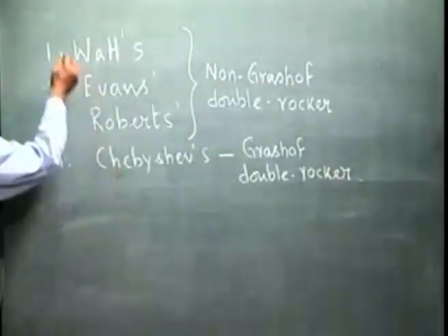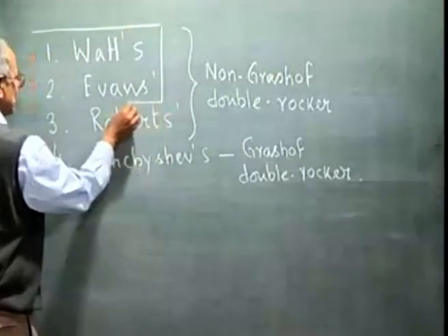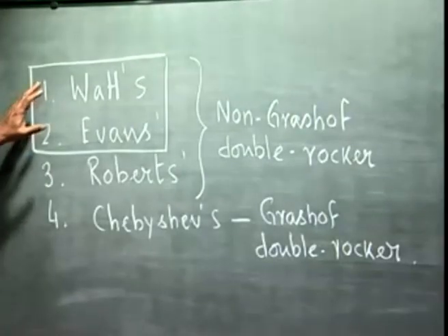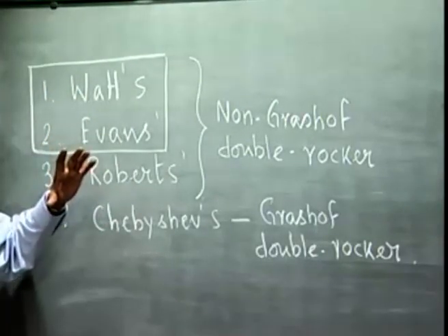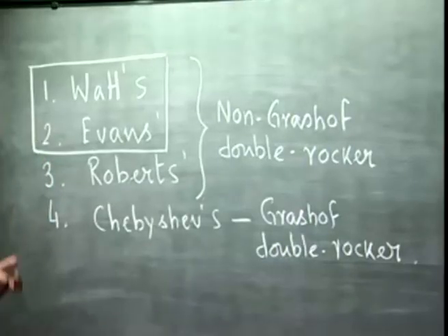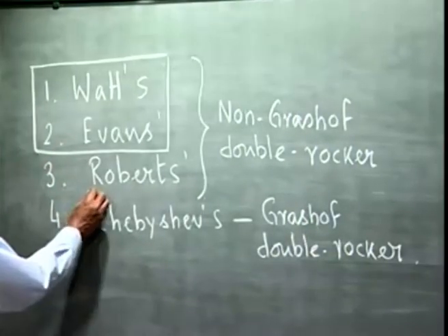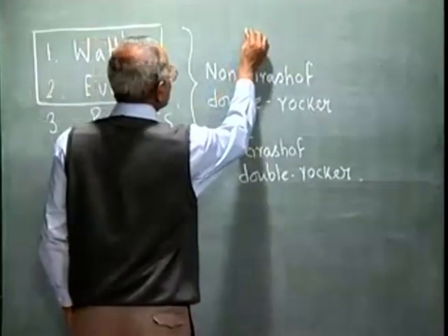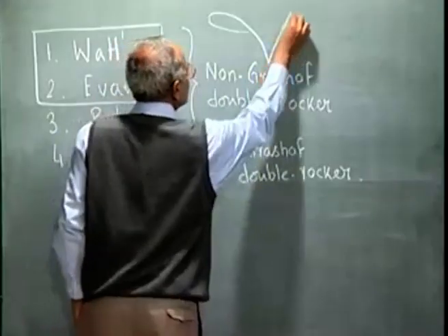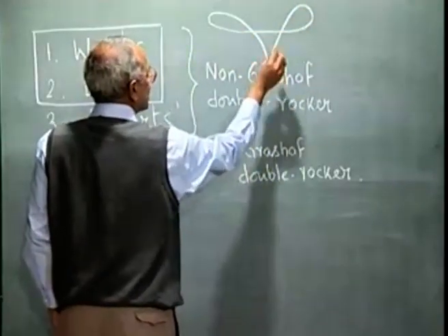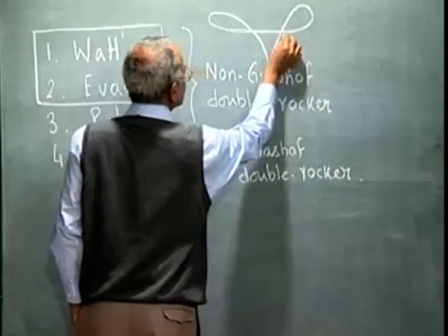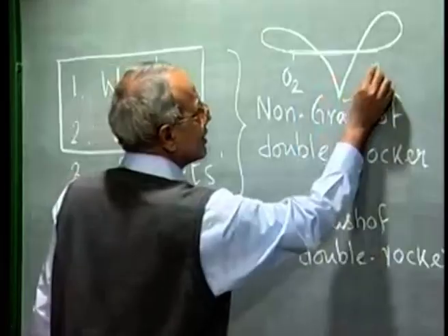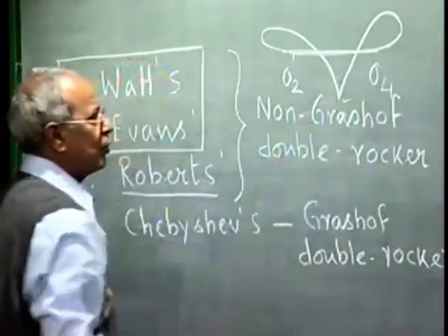If we remember, these two with those particular dimensions mentioned earlier were capable of generating figures of 8, in which a fairly long portion was in approximate straight line. In this Roberts mechanism, we had a cusp, a curve of this type, where there is a cusp and this fairly approximate straight line portion which was coincident with the locations of the fixed links, fixed hinge O2 and O4.